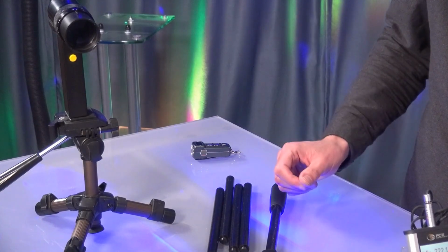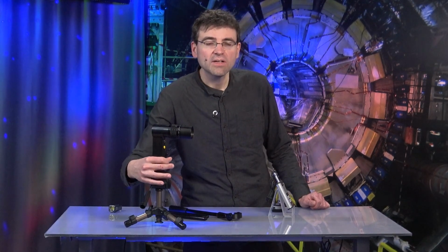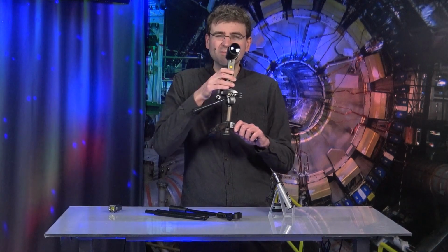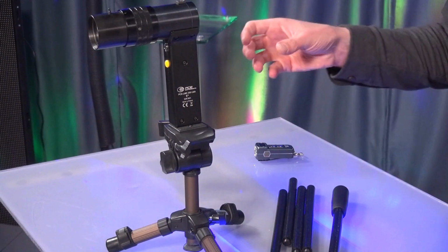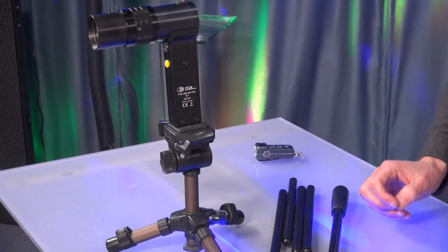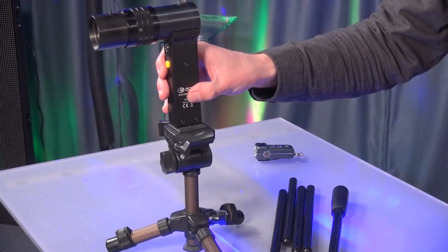There is also an extension for this device, namely a luminance attachment, the PCE LMD LMA1. And it has a 100mm lens with a measuring field angle of 1 degree. And so we are almost able to use it for targeting. With this device, it is possible to measure the amount of light at a very specific location. And I've deliberately put it on a tripod here because with this small aperture angle, it's very, very important to align it precisely to actually reach the desired location.